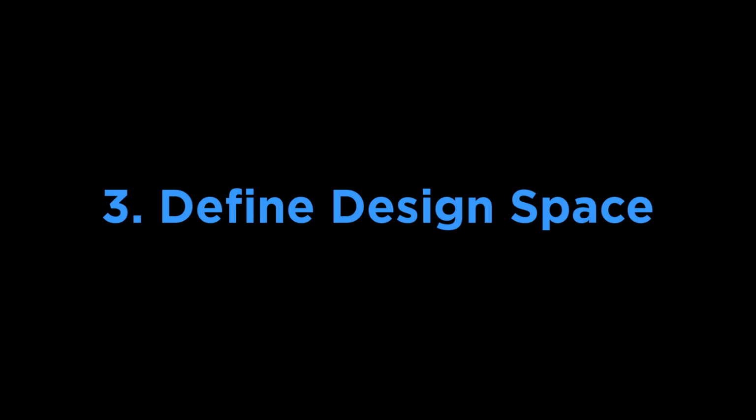Today's tutorial is going to cover the checklist users should follow when performing a sizing run on their models. First, we will import a FEM, then create a structure, define the design space, define the loads, define the failure criteria, size the structure, and then review the results. Let's walk through that process.